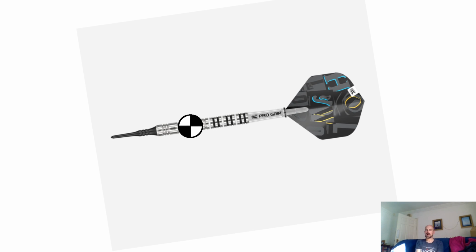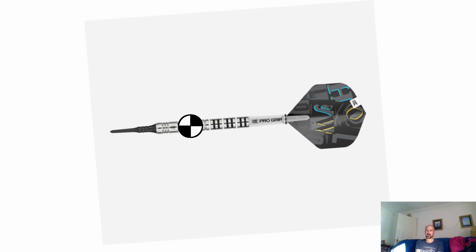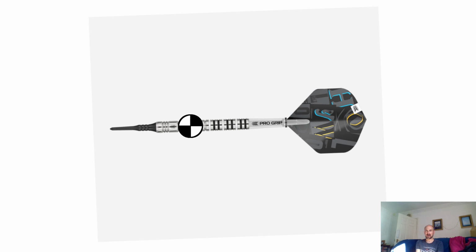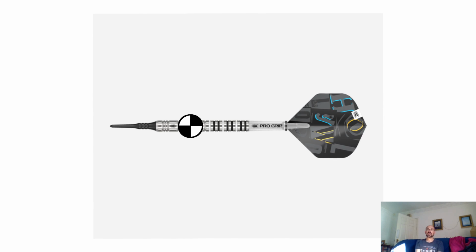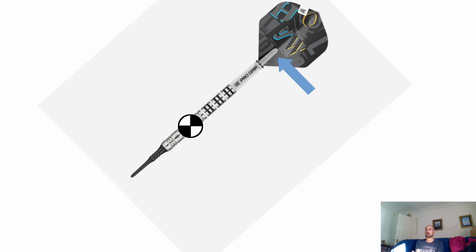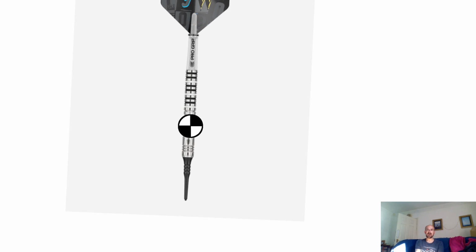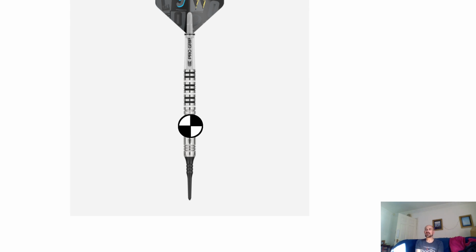Now, the other thing about a dart, of course, is that because that centre of mass is so far forwards, the only things that are anything like wings are on the back of it, well, it's going to keep on tipping itself further and further forwards. So although it's stable, it's never going to reach stability until it's in a vertical dive. So it doesn't generate lift.